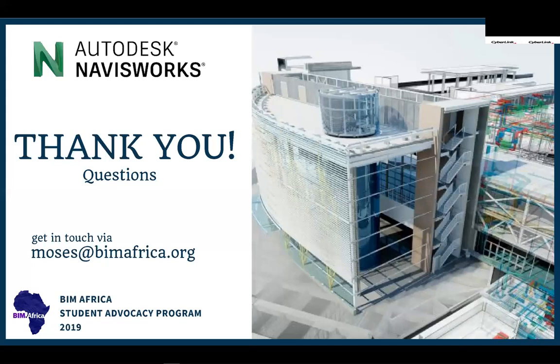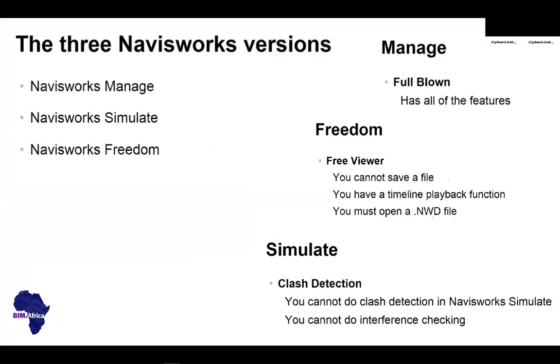But Manage is a total solution where we have clash detection, timelining, quantification, and a lot of other features. But in Navisworks Simulate, there is no clash detection function, and you cannot do interference checking.